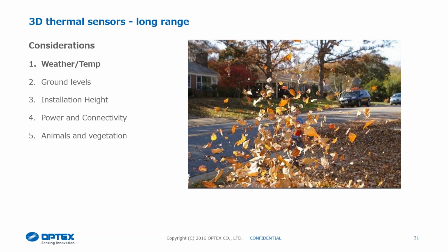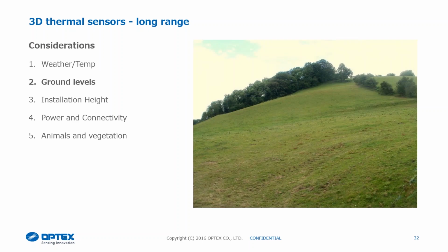Things to bear in mind, any passive infrared detector can get some background interference from weather. So if you are looking at vegetation, for example, that vegetation's blowing around in the background, that's something that you need to bear in mind. With these detectors, you do need to do the training on them. You do need to use the area viewfinder and a walk tester to be able to set them up correctly. Once you set them up, typically you can actually filter out 80 to 90% of the false alarm causes, and they are a very, very stable detector.